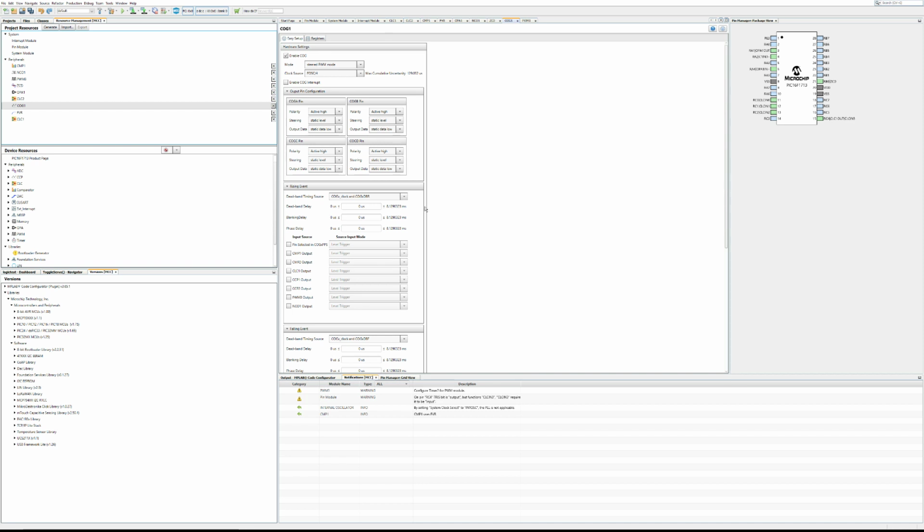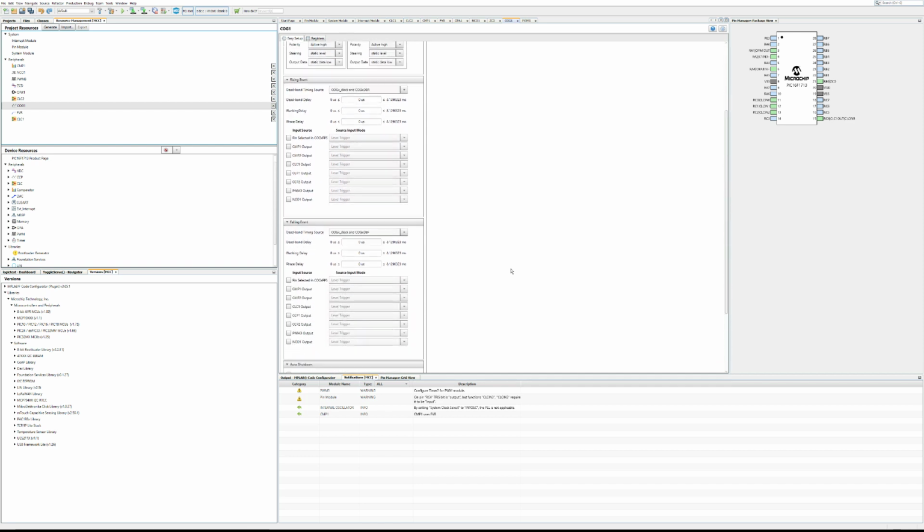Using the complementary output generator, you can use one PWM signal to drive both gates and provide a deadband between them, so that there will be a time when both gates are off before transitioning to one being on. So that then prevents shoot through and other nasty side effects, as well as you can do blanking and phase delay. It's a very complex sort of beast, but again, can be useful if you are in a situation that you need something like that.